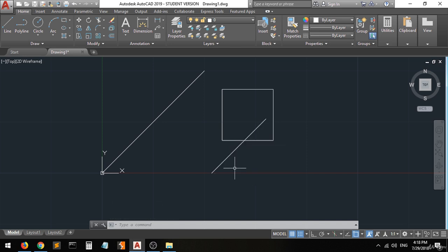Okay? Now, as you can see, using the at sign will do it relative to the start point. But when you don't use the at sign, it will be calculated from the origin. Be careful. So, if you do this, select the line and then specify the first point, not picking any point from here.